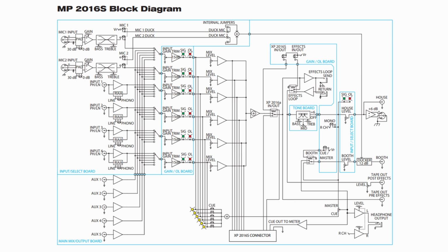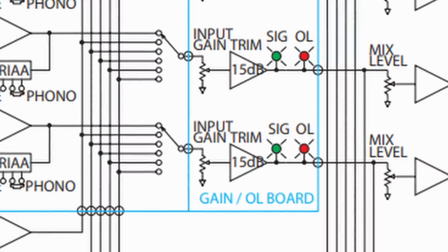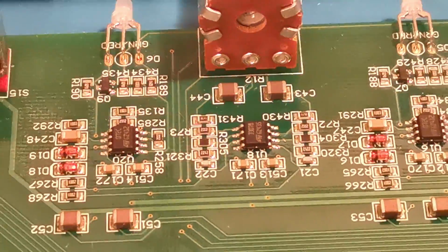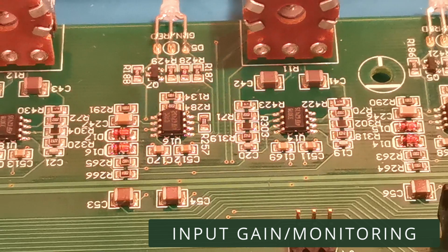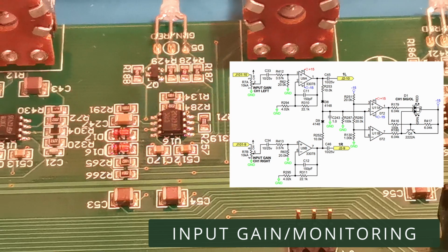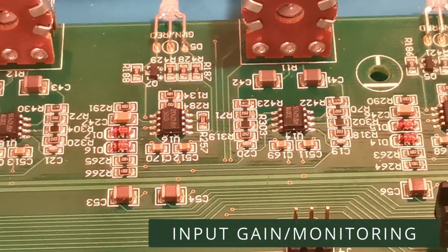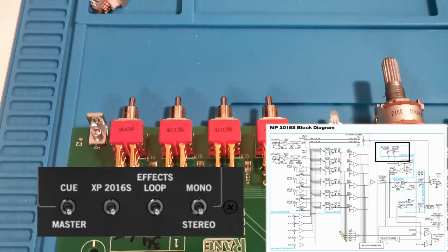Let's get back to block diagram and see where the input signals go. They go to the input gain and monitoring section. This section is placed on the smallest of 3 boards and is very simple and straightforward. The gain module is based on 33078 op-amp. I think that the secret of this mixer's sound mainly lies in those chips. Gain circuit is just a passive attenuator followed by a voltage amplifier. Thanks to this we can attenuate and amplify the signal. Monitoring section uses op-amp as a comparator and glows the LED when a certain voltage level is exceeded. On this board we can also find some switches to control some things.